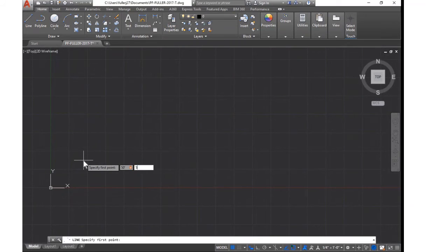And I'm going to also type 50 feet in that one. Okay, and that's going to get me in that specific position. Click enter. Okay, so that start point of my line, where that line is stuck to right now, is basically 50 feet by 50 feet from the 0 axis point down at the bottom left.